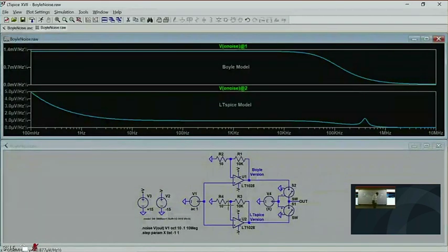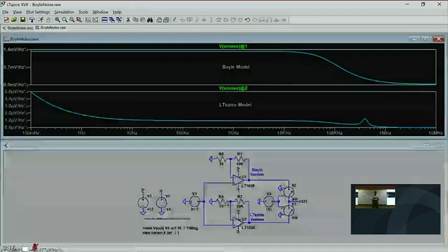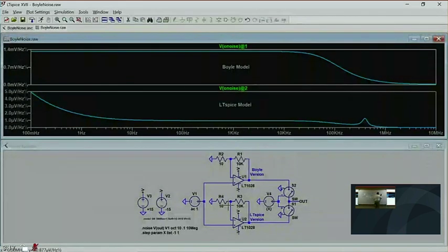Let me give an example of how that happens. Consider a rail-to-rail input op-amp. Now in op-amps, when you hear rail-to-rail op-amp, usually that's probably just rail-to-rail output, okay? But if you have a rail-to-rail input op-amp, the way they're implemented is two different input stages. So you consider here an N stage. These plus and minuses will be the rails. All right, here's the input.